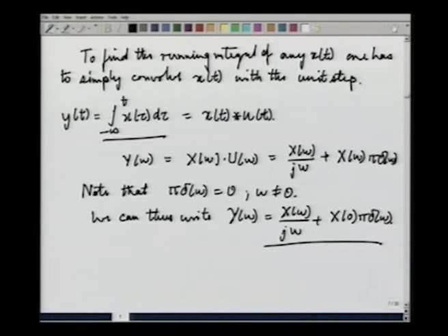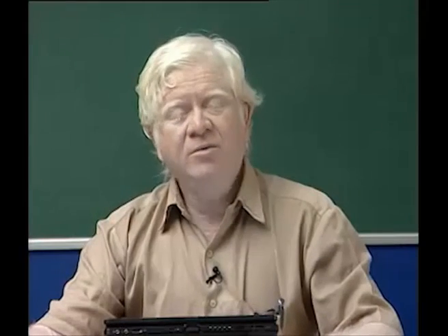All right. Now, one final question: does this all tie up properly? We had x1 t equal to x t, where x t was taken to be a 0 average signal, and therefore, x 0 was 0. And then we had x2 t, which had an additional DC component of c.